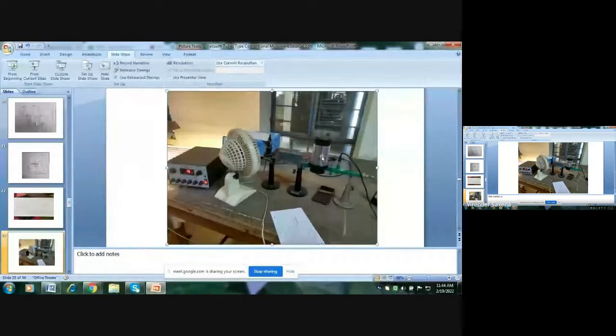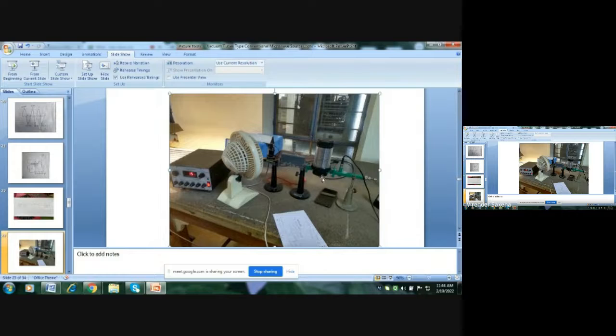When this cavity is matched, or frequency of this cavity is equal to the frequency of the microwave, then power enters in the cavity. Power is absorbed by the cavity due to resonance, and we will get less power in the detector, and there is a dip. There is a minima in the deflection meter. So this frequency is directly read over this scale.